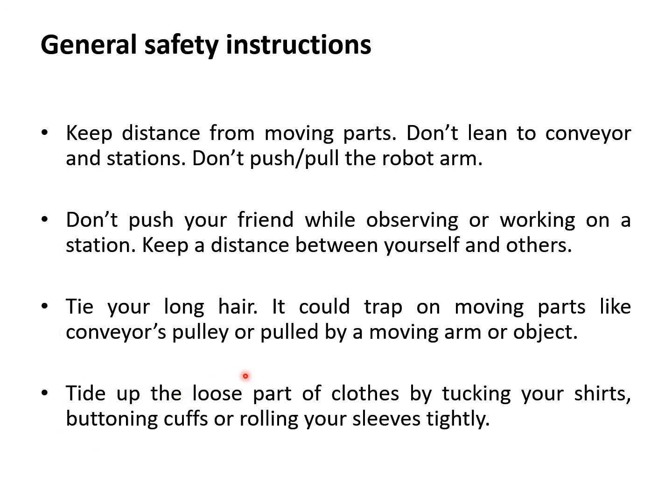Tie up the loose parts of clothes by tightening your shirts, buttoning cuffs, or rolling your sleeves tightly. Usually operators and workers wear a specific work suit, but even on those you should be careful that there shouldn't be any loose parts.